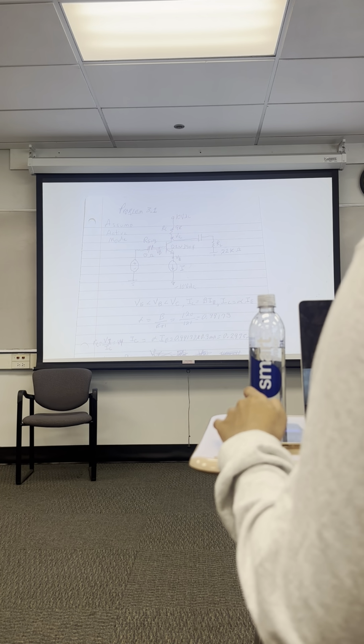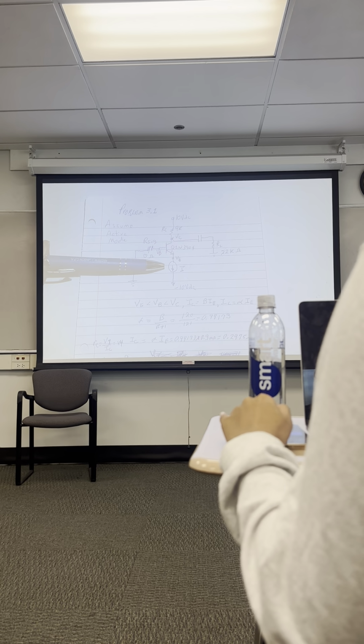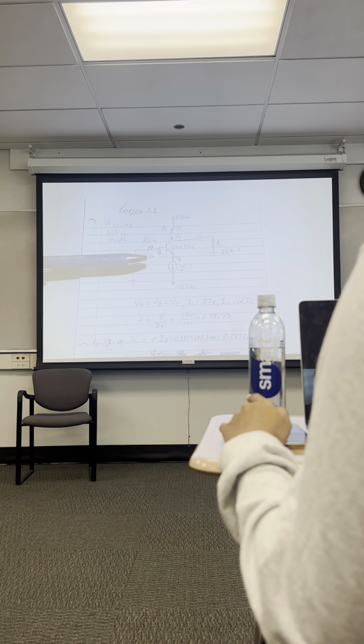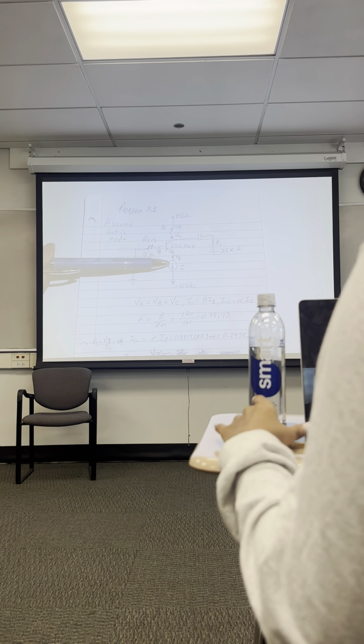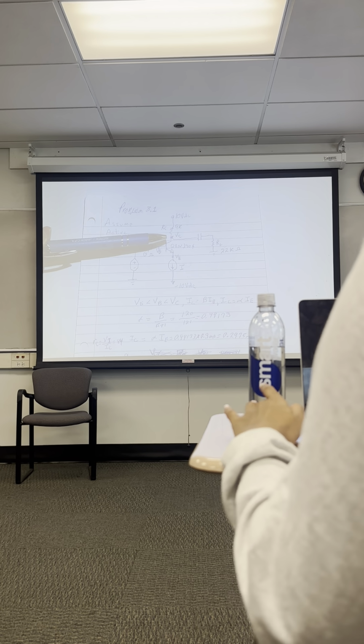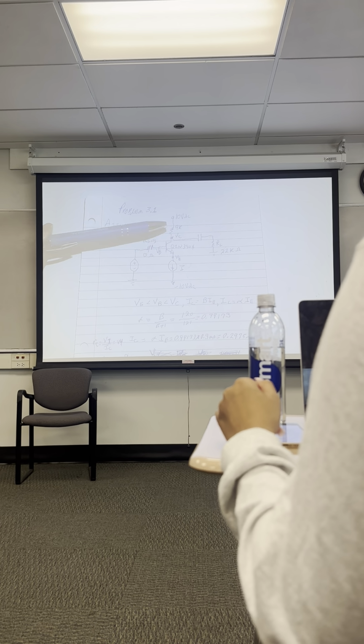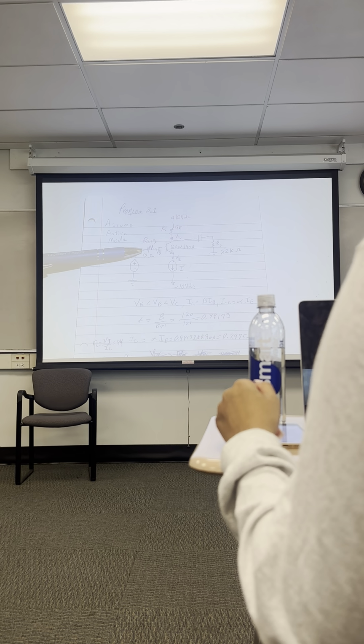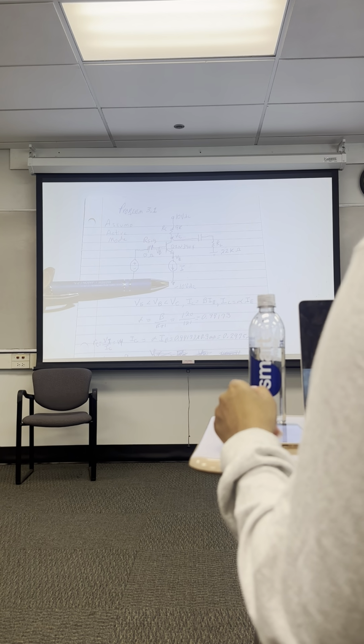In this circuit, you're given the emitter current. You don't have to solve for it. You have to solve for the emitter voltage, the base voltage, and the collector voltage. So what is the base voltage on this? You notice here what that little arrow means? It means that this is connected to minus 10 volt DC. So it's a dual polarity amplifier.